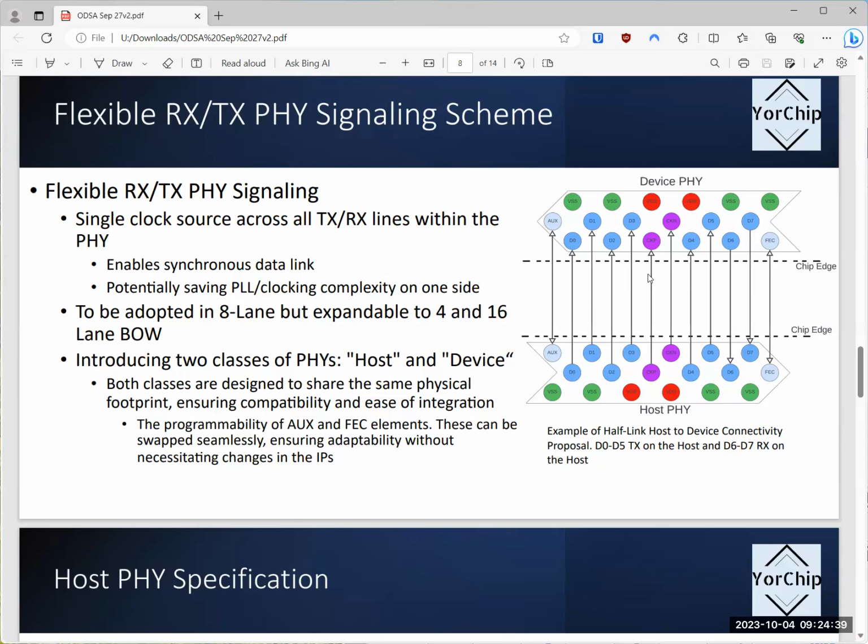And then the extra mode is that, yes, you can partition within the 2x4s within each other, to become more TX or more RX, as the case may be. But I think if somebody's building a bidirectional, quote unquote, normal PHY, this would be a more straightforward thing for folks to reuse. And it does give you the capability to interop with normal other things on the other side, only paying the extra 2 bumps out of 10. So it becomes 12 bumps instead of 10.